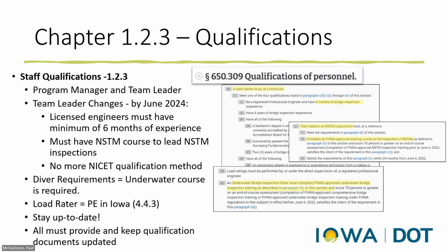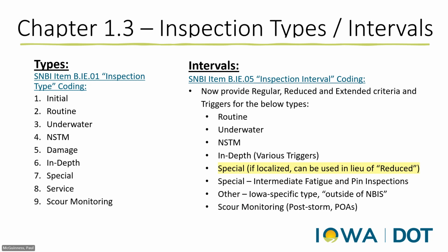For team leaders to lead NSTM inspections, they're going to have to take and pass an FHWA approved NSTM training course. That's the old fracture critical. Similarly, if a team leader is going to lead a dive inspection, they're going to have taken and passed an FHWA approved underwater bridge inspection training course. Load rating engineers, they're going to need active Iowa PEs, and all certs should be uploaded to SIMS and updated as required. Next.